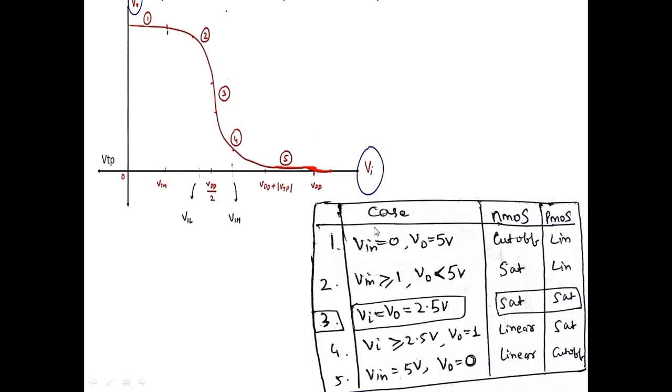So for example, select first I'll keep V equal to 0 and then I'll increase this to 1 volt. And still further increase this to select V equal to 5 volts. So upon the increase of V in voltage, say from 0 to 5 volts in different values, what is the amount of output voltage obtained, as well as how these NMOS and PMOS devices will behave, or in which region of operation will these NMOS and PMOS devices be operating.